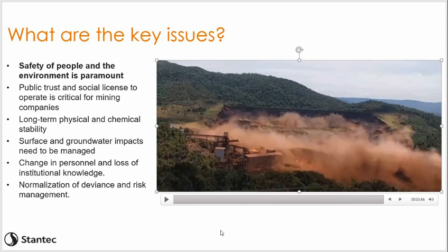And some of these issues that can occur with these facilities, of course, are long-term physical stability. As geotechnical engineers, this is really one of our bread and butter items: slope stability. So, you know, are we managing water appropriately? Are we developing saturation within our facility? Is there a liquefaction potential? So on and so forth. There's obviously a chemical element as well in mining, with all the use of chemicals to extract the minerals and the natural chemicals that occur within these ore deposits.